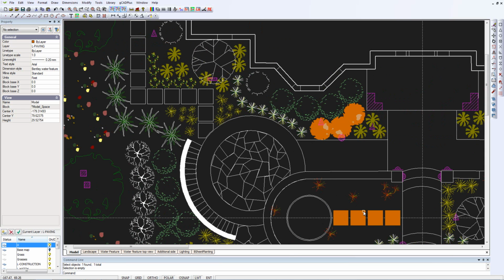if we extracted the blocks on the paving layer, we would get 4 blocks of that 2-foot square paver name in the file that we bring to Excel. So we could do a quantity of pavers needed for this design once this part has been built in.